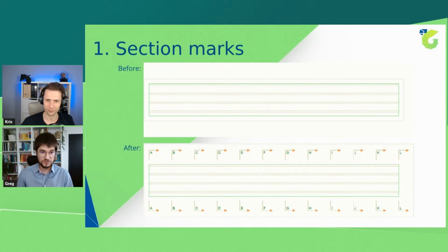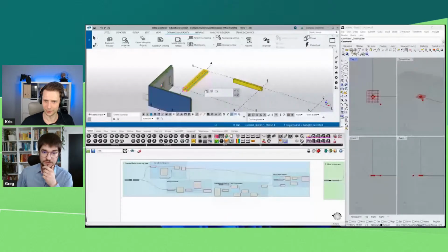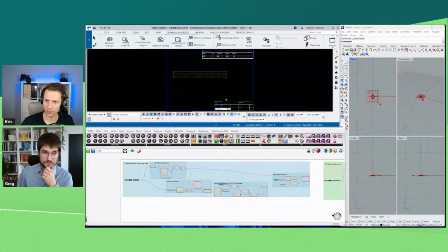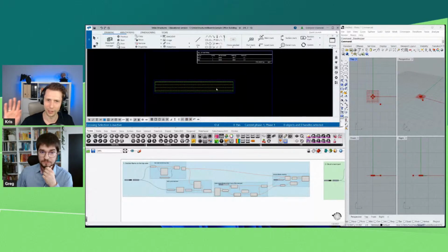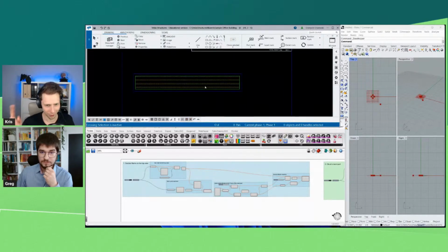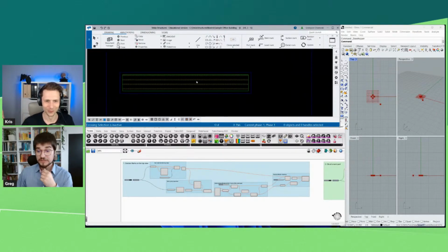So, Chris, if you can just change the screen. Yes, we are seeing your screen right now. So we have Tekla, which we have to open first, and then Rhino and Grasshopper, the same procedure. It will not work if you do it the other way around, right? Exactly. The underlying Tekla Open API works the same for both types of connectors. So here we are seeing just a linear example.